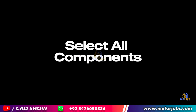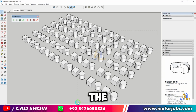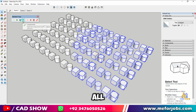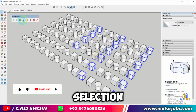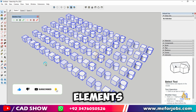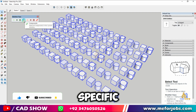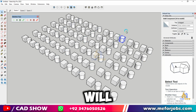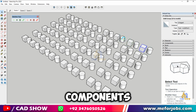Number 4. Select All Components. With the Select All Components in Current Selection tool, you can easily isolate all components within your selection. This is particularly handy when dealing with repetitive elements or when you need to modify specific components. Select the desired part of your model, click on the Select All Components icon, and all components in your selection will be highlighted. This tool is invaluable for tasks like batch editing or inspecting components.